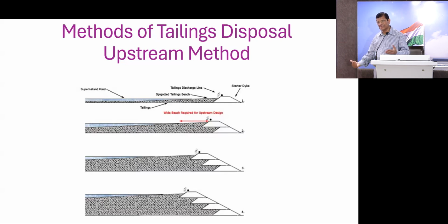The foundation is the tailings. Initially, the person who gave this concept considered it very economic, because except for the starter dam you don't need anything, everything is there, and while you are building it, your space is still confined. You are not going into more space; rather, the space is reduced a little. But the problem is that the foundation is the tailings.